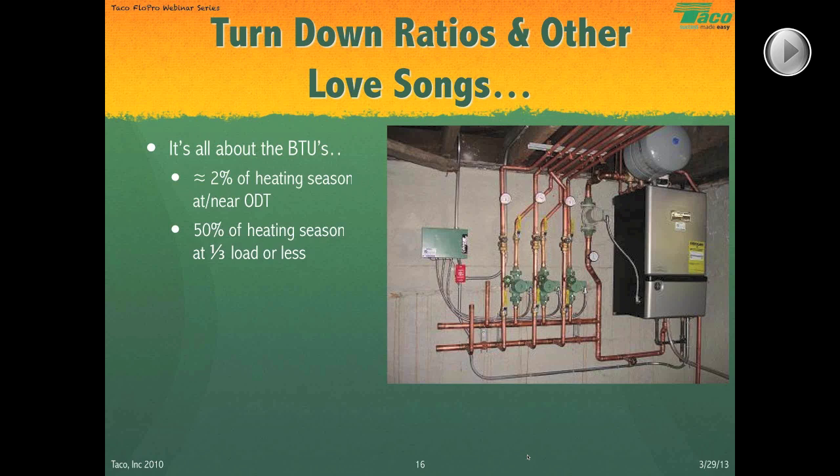You have those situations. But more or less, 2% of the heating season is at or near design conditions. The other side of the coin is that 50% of the heating season, a full half of the time, over the course of a heating season, you are at 1/3 of the total load or less.